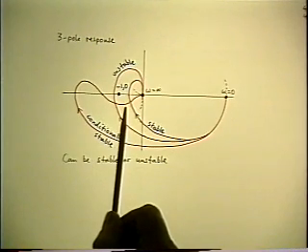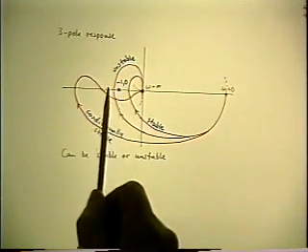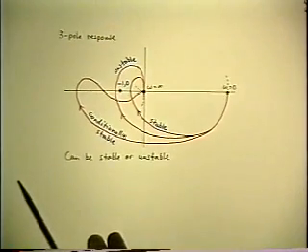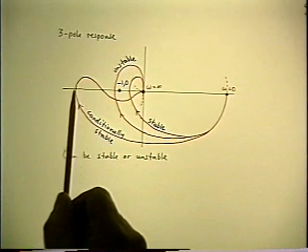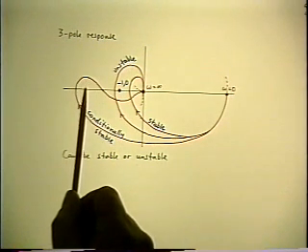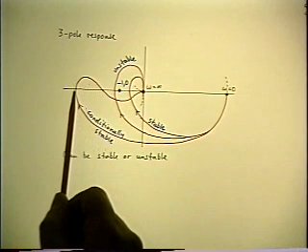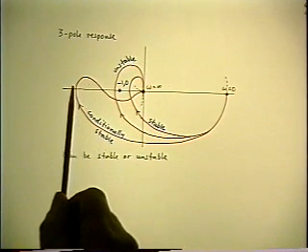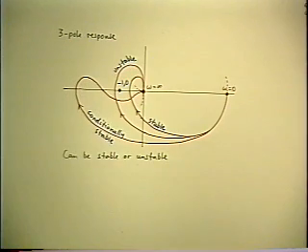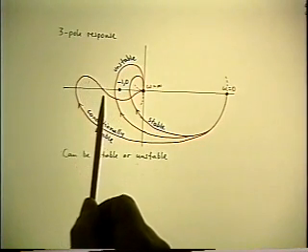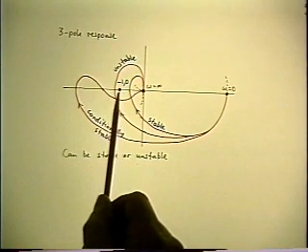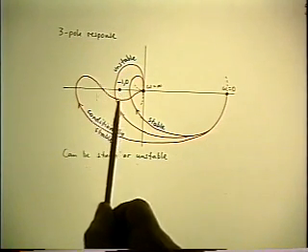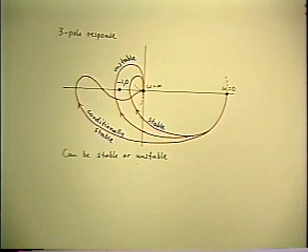According to Nyquist, it's stable, because it doesn't go around the -1 point, but it has the peculiar property that the phase angle has actually increased beyond 180 degrees, while the magnitude is bigger than 1. But what saves it and makes it stable is that the phase comes back below 180, and when the magnitude is going through 1, the phase angle is below 180, which is what makes the contour avoid the -1 point. So that's known as a conditionally stable system,